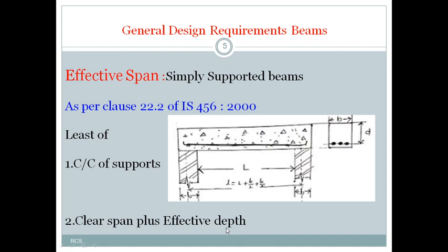You know what the definition of effective depth is? Effective depth is nothing but the distance from the topmost fiber of the compression zone to the centroid of the steel reinforcement. So this is the steel in the longitudinal section. We can see here the steel reinforcement provided, and here 3 bars are provided. Those bars are behind this, so we cannot see them in the longitudinal section. Those bars can be seen in the cross section. So 1, 2, 3 are provided. The effective depth is from the outermost fiber of the compression zone to the centroid of the steel reinforcement. This is called effective depth.